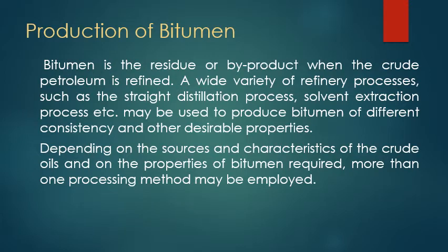Now coming to the production of bitumen, as I have discussed, bitumen is a hard hydrocarbon material of natural or pyrogenous origin found in gaseous, liquid, semi-solid, or solid form, and is completely soluble in carbon disulfide and carbon tetrachloride.